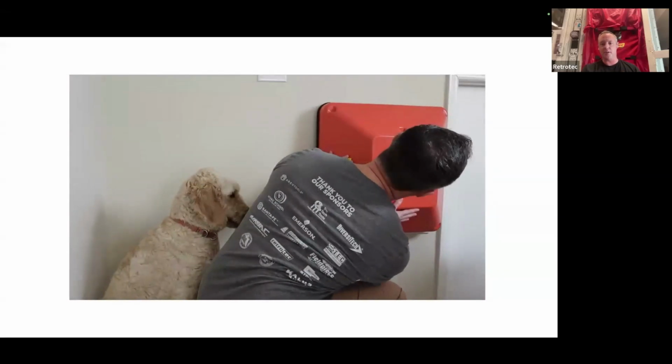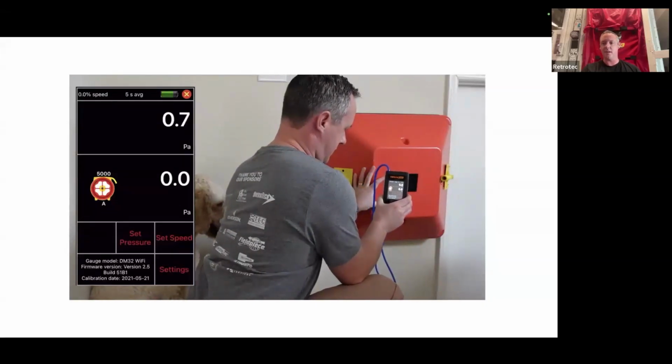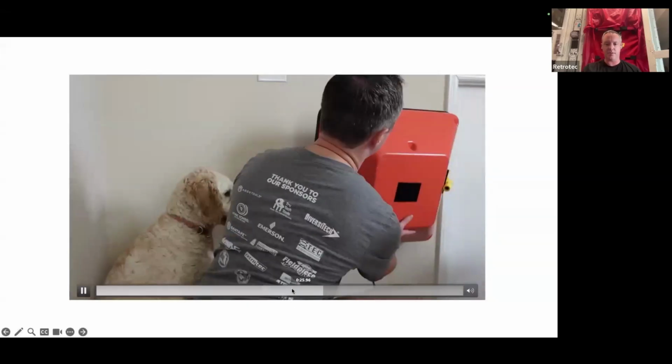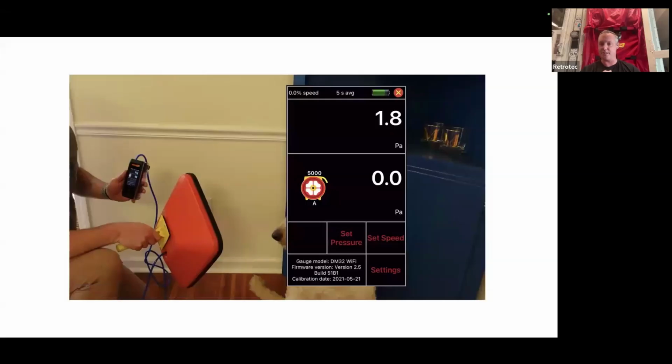The bigger one here for the return, we're only getting just under 1, so not a lot happening with that one. And if you're curious what was going on here, the foundation type changes from this floor to the next room over. The next room over used to be a screen-in porch, and the previous owners enclosed it. So it goes from a crawl space to an elevated slab, and that connection is really leaky. So air dumps into that wall from the bottom. We were able to see that easily from the top of the pressure pan.